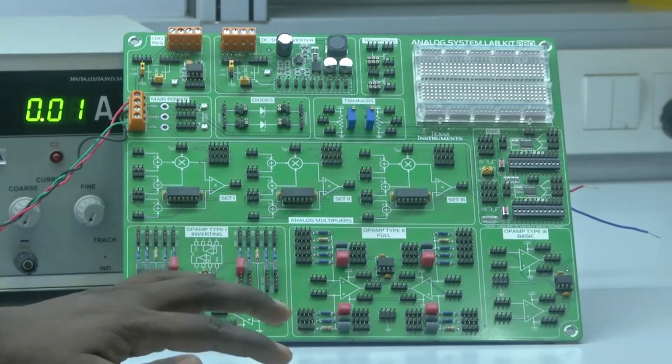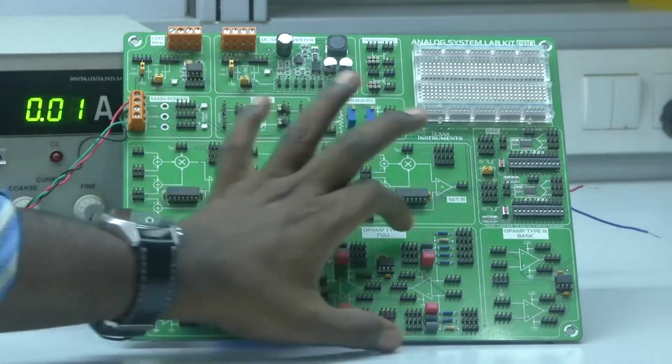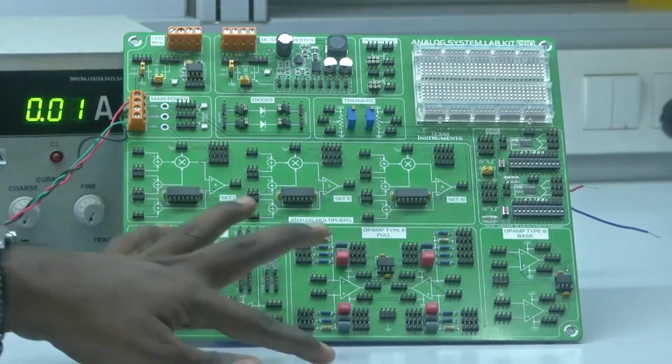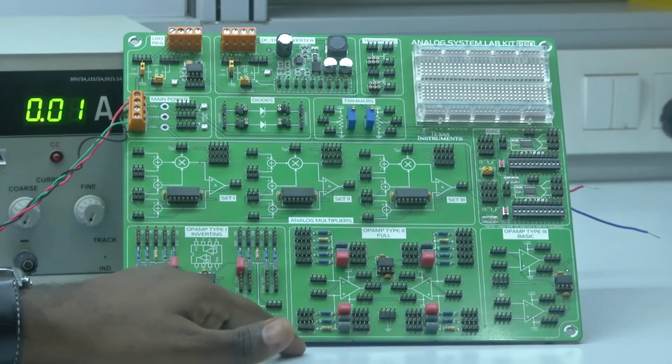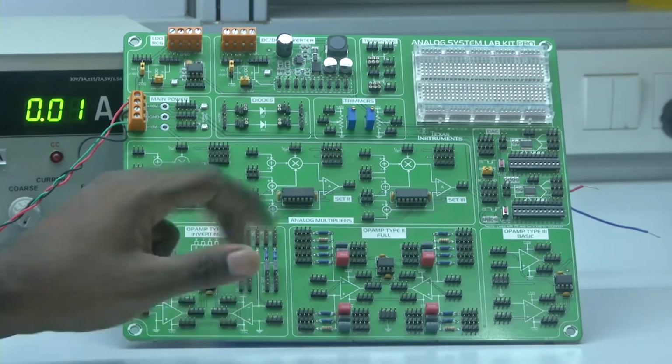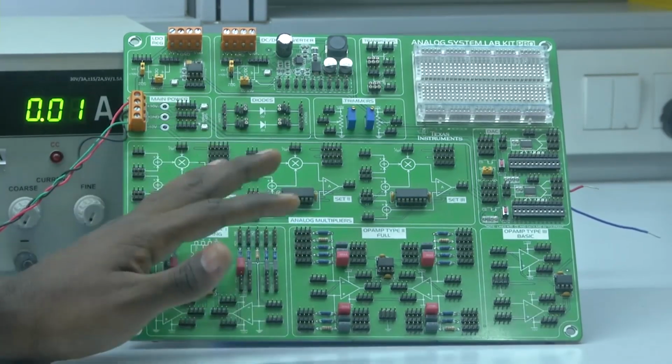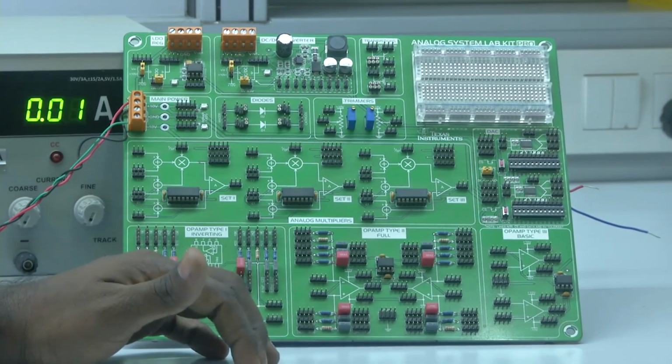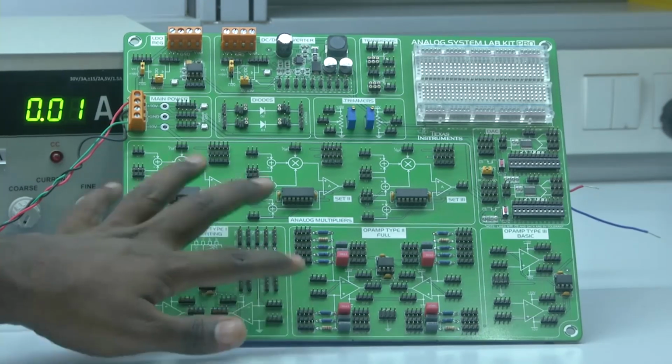Now what we do is that we will use this particular configuration, either this or this, and we will implement both the inverting amplifier configuration and the non-inverting amplifier configuration. We will see whether the designed circuit is giving a gain of 10. How do we test it? We will apply a known input voltage, measure the output voltage, and the output divided by the input gives the gain of the complete system. By looking at that, we will see whether we have achieved the targeted gain, that is, whether the practical gain and the targeted gain are the same or not.